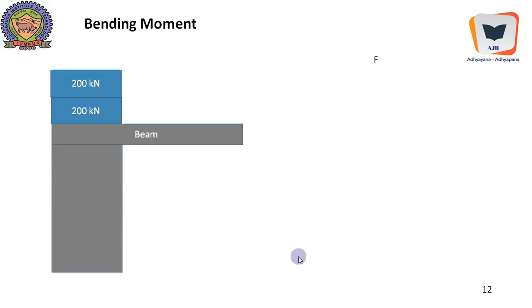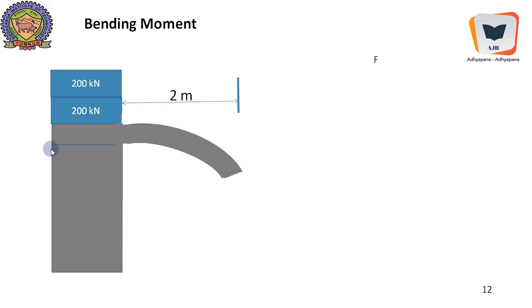Now, we will talk about bending moment, the heart of the matter of this particular tutorial. There is a beam, a cantilever beam. It is fixed through adding the weights over here or by some means, and we will apply the load over here. Immediately it will create a reaction, a vertical reaction. It will also create a moment of fixity. If this is clockwise, it is going to create an anti-clockwise support. Anyway, it will bend. It will sustain as long as it can, but it will bend.